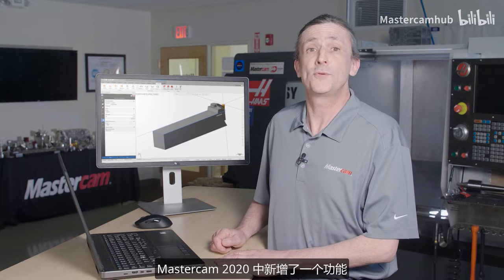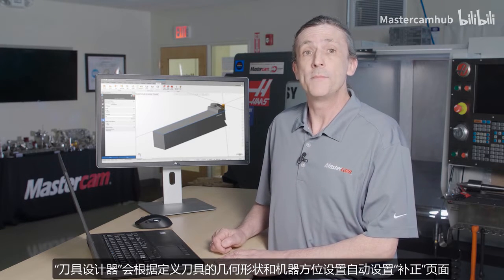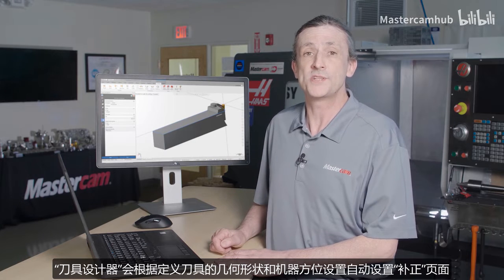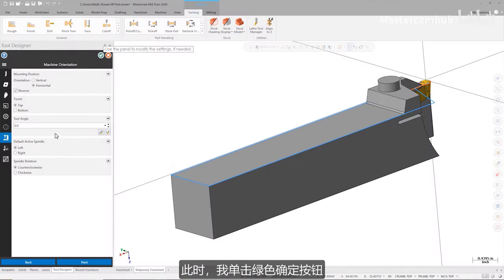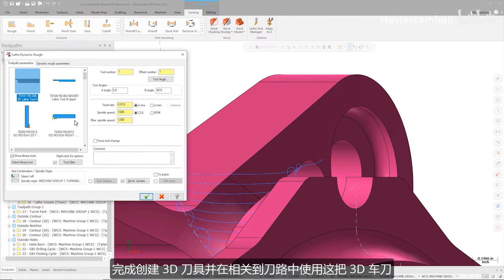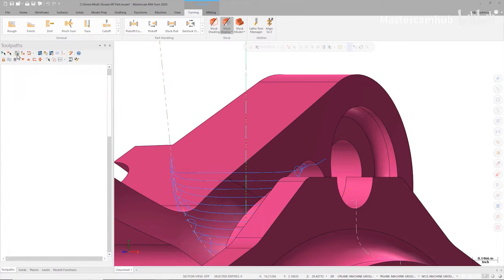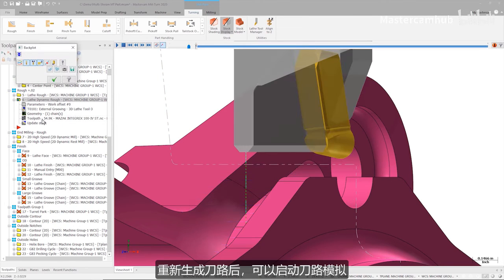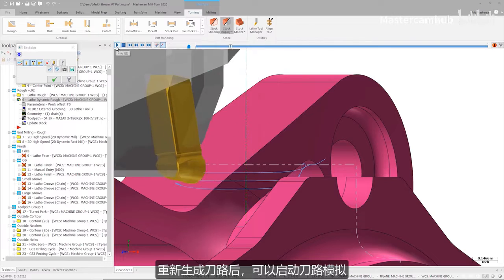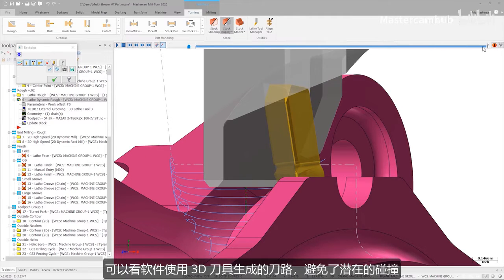New in Mastercam 2020, the tool designer will automatically populate the compensation page based on the tool geometry and the machine orientation settings you defined. At this point, I can click the green check to finish creating my 3D tool and select it from my tool path. Once the tool path is regenerated, I can launch backplot, and the tool is now properly represented, which means the false collision is no longer displayed.